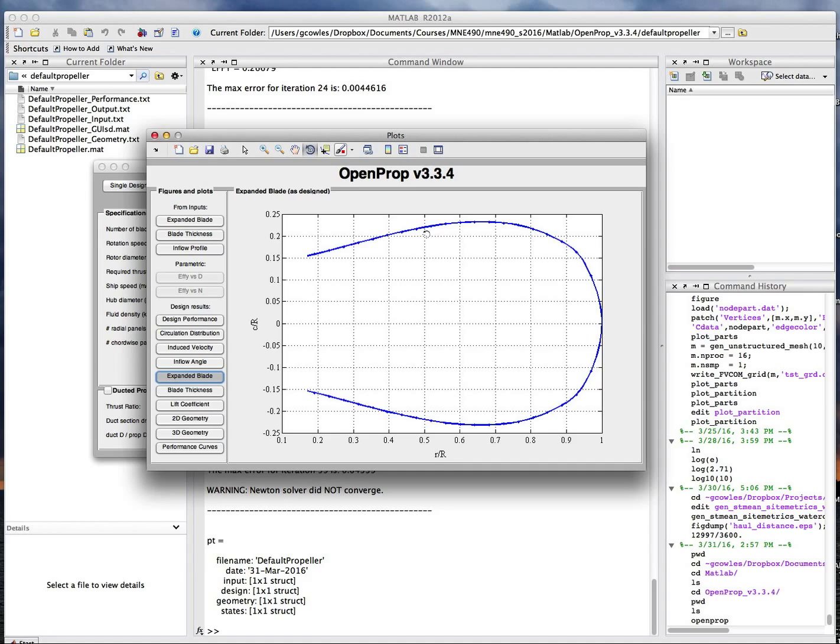So this is the area if you unwrapped the propeller, or basically cut the blade off and hammered it flat on your desk. I guess that's what you would result in, this expanded blade area right here. So it's not the same as projected.